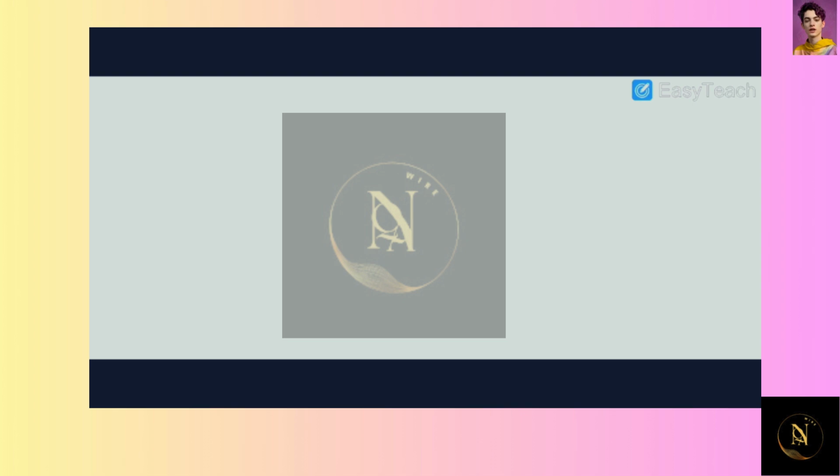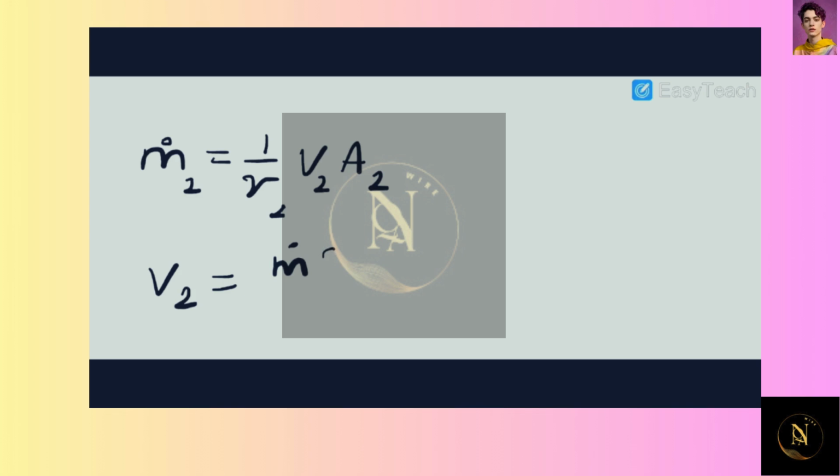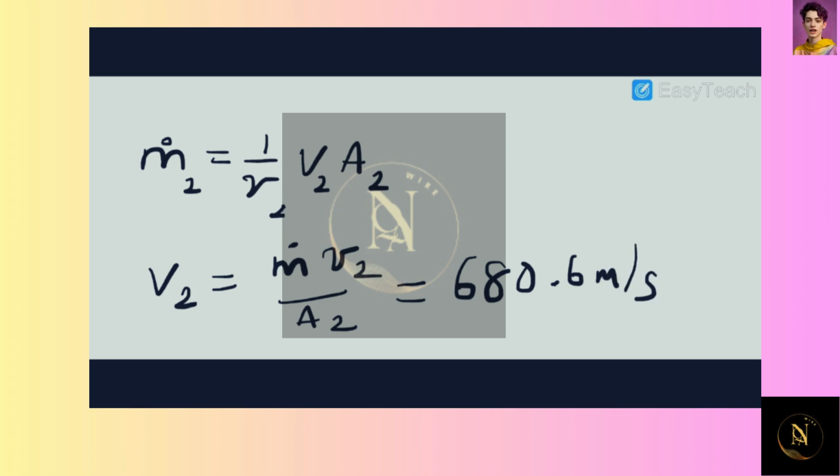Now, since we are operating at steady state conditions and there's only one inlet and one exit, this mass flow rate is also our exit mass flow rate. So we can use this to determine our exit velocity. So m dot is going to be equal to 1 over v times velocity times area, and we can put in subscripts here to designate we're looking at the exit. So solving for our exit velocity, we see that exit velocity is equal to m dot times specific volume 2 all over area 2. We have all this information, so we can compute velocity at 2 to be equal to 680.6 meters per second. And that's another part of our answer.